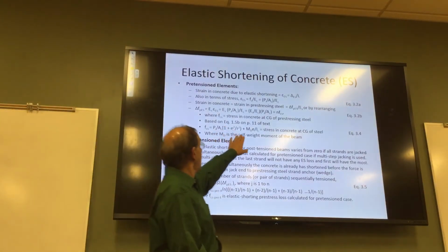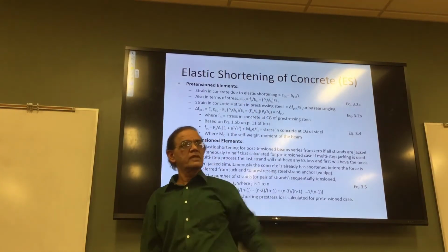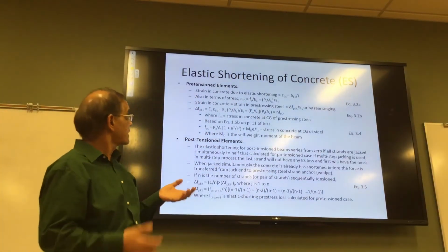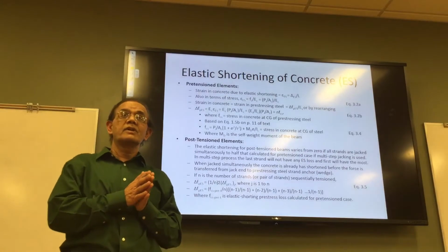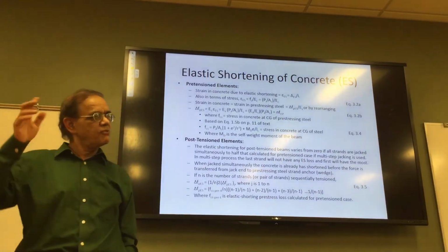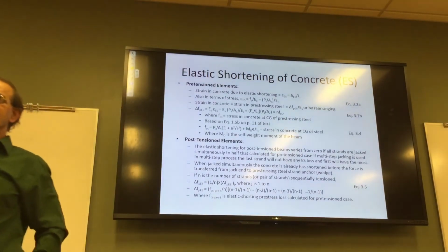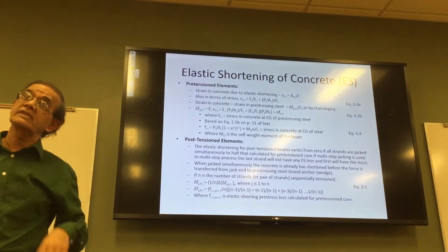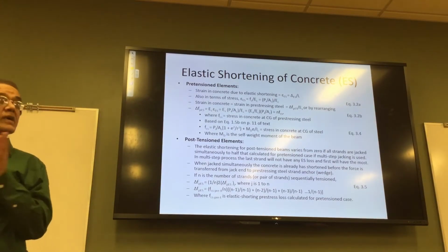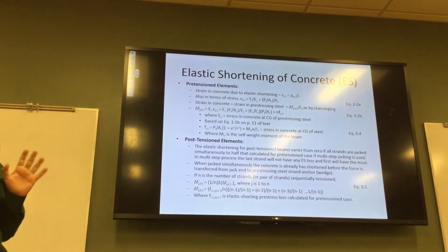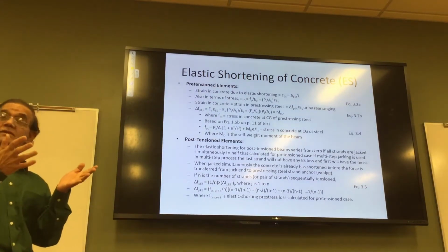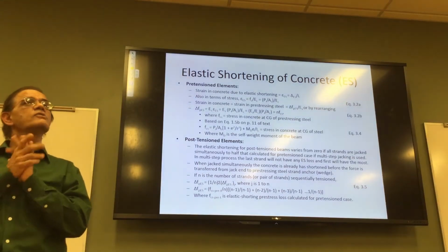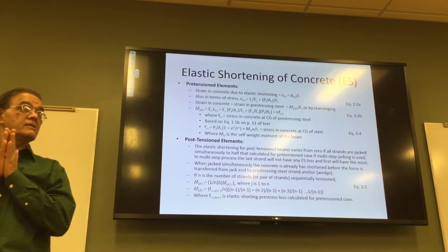Otherwise, that ES is always the same number, 27 or 29, not much different. But concrete is complicated, because concrete depends on a formula, 57,000 times the square root of f'c and all that. And depending on the water-cement ratio, there is a more complicated ratio, depending on what you got. So depending on the strength, there are different formulas. So you watch out how you calculate EC.